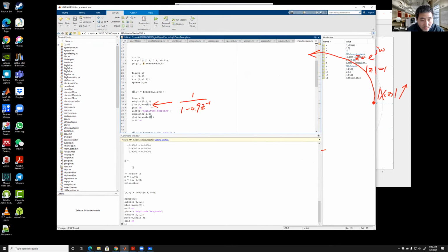All right. So on the second part here, what I did is freqz, frequency Z. We showed this once before. Freqz is going to show me a spectrum. I'm also using polynomial coefficients b and a. H is the value, W is the frequency. So I plot W, and the absolute value of H. The top picture should give me the amplitude, or the magnitude. The bottom picture is the angle of H, so it gives me the phase of my output.